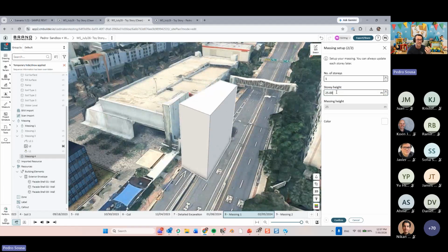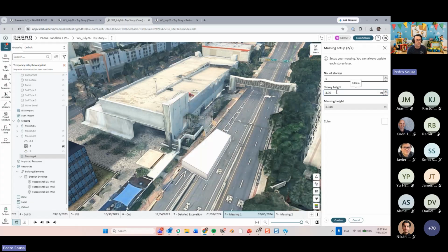Okay, so I can go ahead and put in some operations in here that will solve that operation and give me the result. But one thing that not a lot of you knew is that if you're working in meters, but you want to use feet as an example, I can just put in 10 feet over here, FT. And when I hit enter, this converts the value for me automatically. So use that, let us know how it works, and so on and so forth.